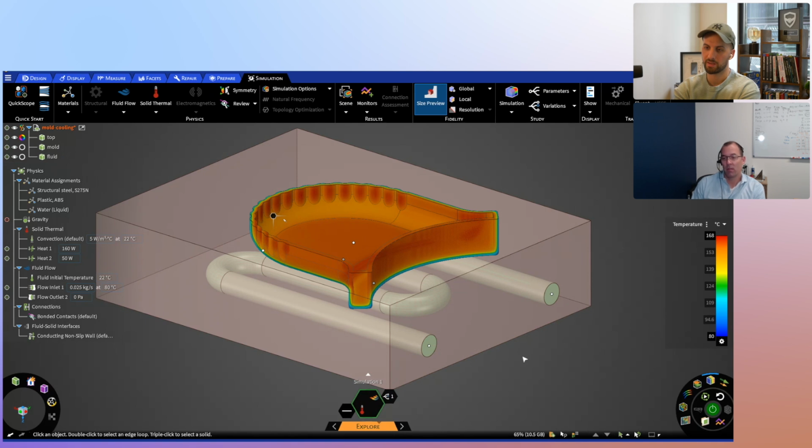They have. And this GPU solver, again, I don't work for Ansys, so I can't speak to any core intellectual property. But there's a lot of capabilities in Discovery because I may not be expecting to match this to test data per se. If I put a thermocouple on a forced convection model, which is simple physics, we're not pushing the limits of physics or math at all, within a few percent. There's case studies of it matching Discovery to Fluent and Fluent to test.